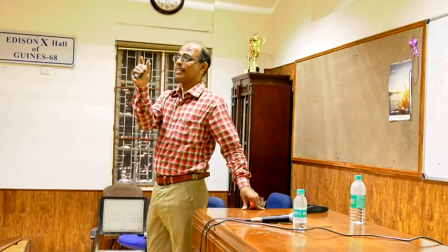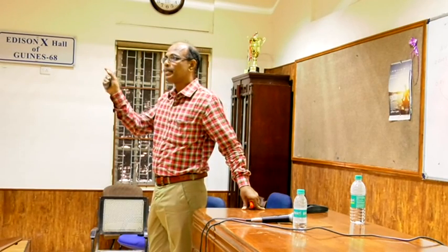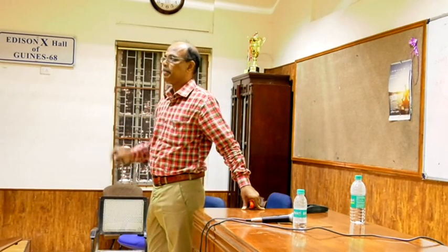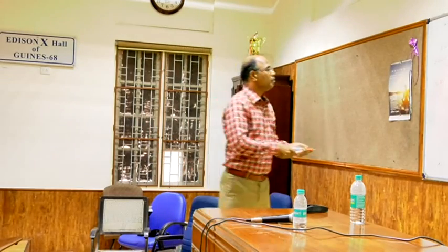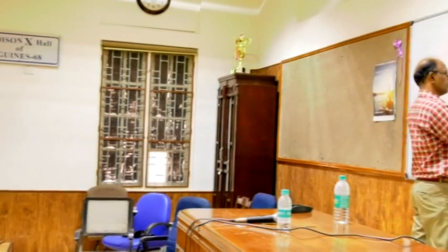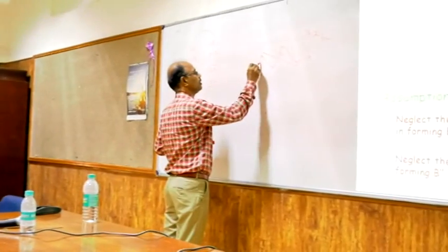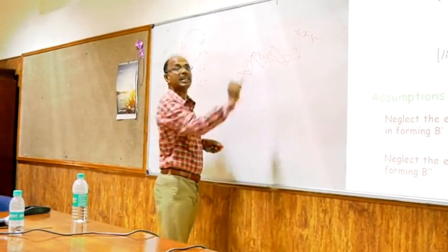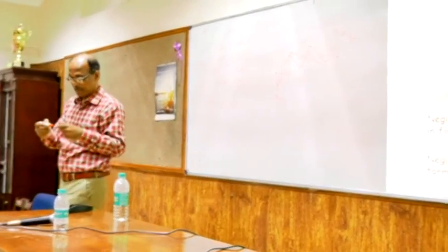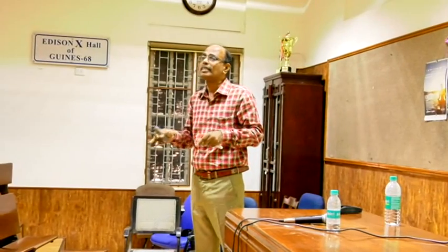It is the fastest, but it takes more iterations. Newton Raphson takes 3, decoupled takes 7, this takes 50. It takes more iterations because it involves large approximations, but it does not require any formation of the Jacobian or any inverse of the Jacobian. So the overall execution time is 1/10 of the Newton Raphson method, and still it gives a good solution.